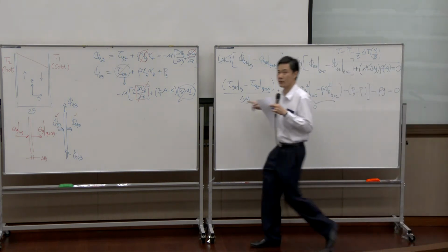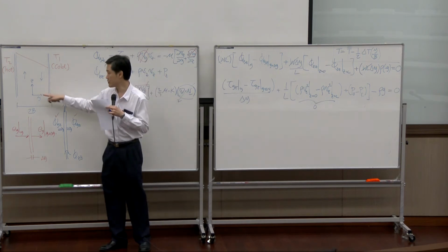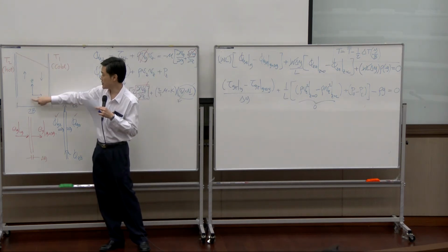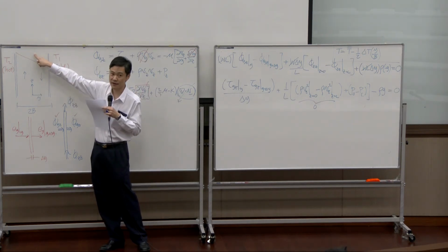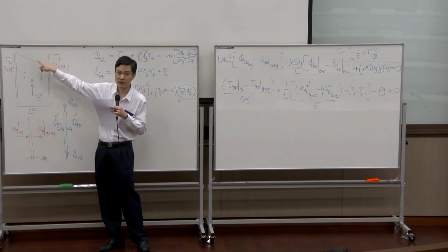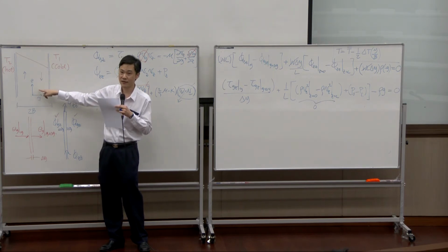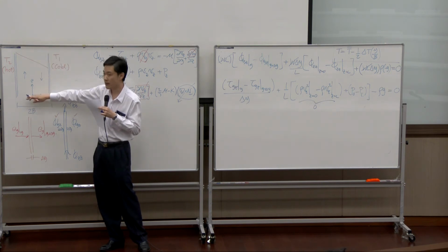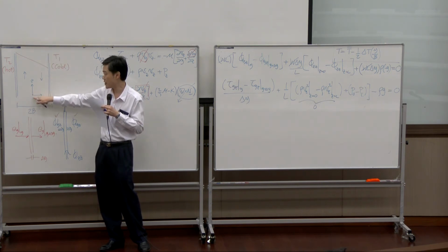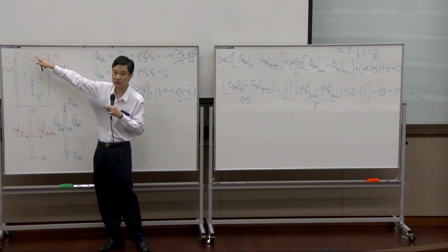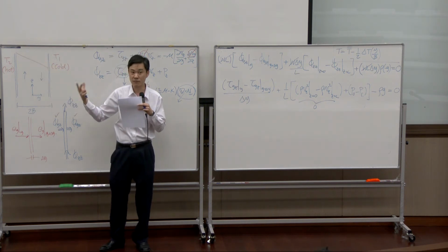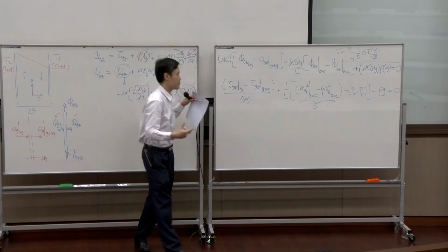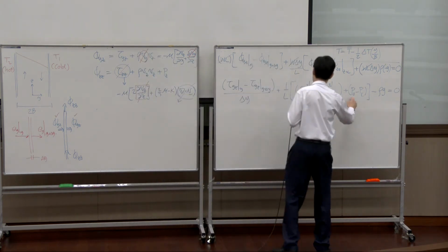Now let's go back to the picture. P0 is here, PL is there. Do you think pressure is different? Yes, they are different. There's a head of liquid pushing on top. So pressure down here is supposed to be higher than pressure over here, even though we did not supply any pressure. So pressure is not canceling each other.